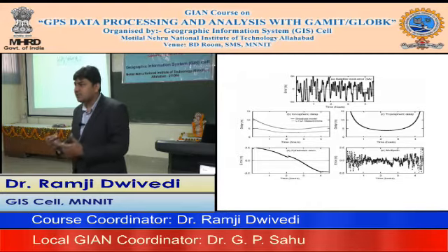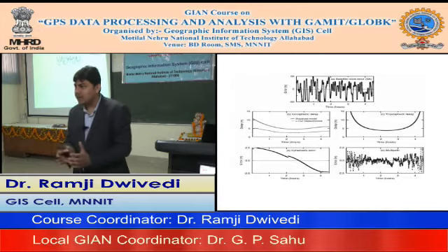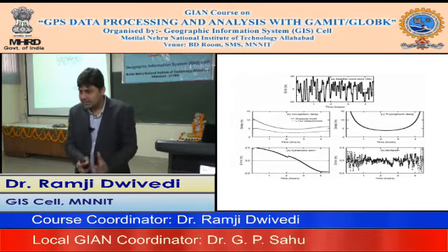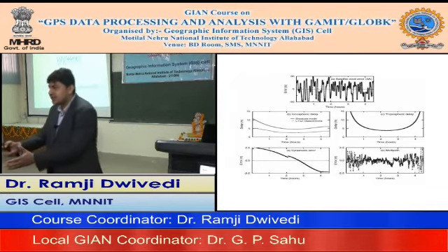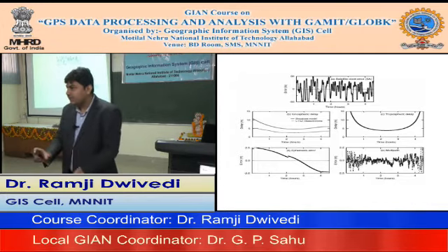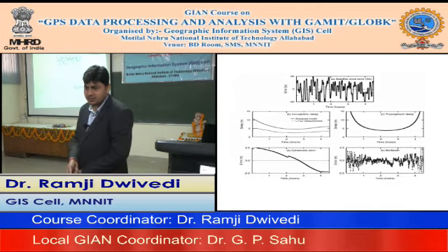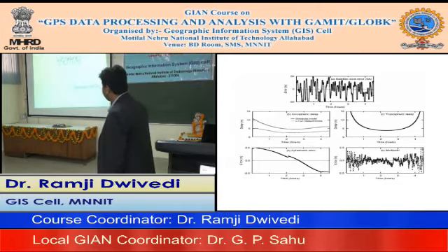So broadcast ephemeris gets updated in terms of those parameters. The moment you use those parameters to estimate x, y, z of the satellite, and the moment you have the next ephemerides, you have new x, y, z. So possibly there would be a little shift in the position of the satellite in the ECF coordinate system.